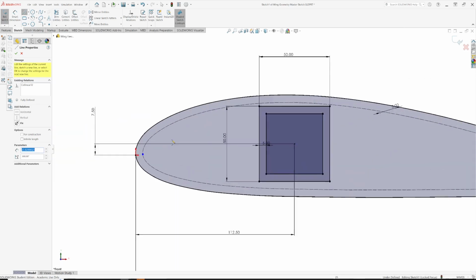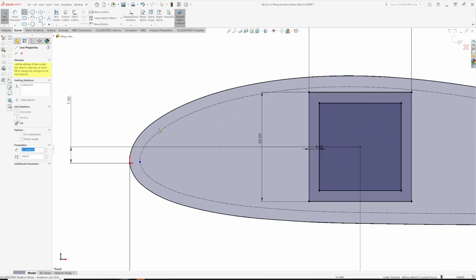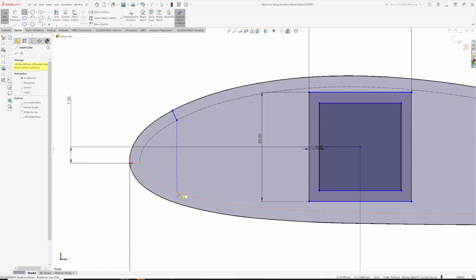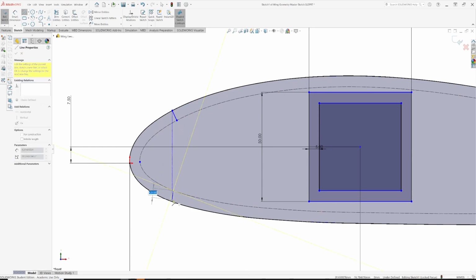The other thing we need to do is a leading edge part, because if you're covering this, you can't just have film coming around a curved edge like that. It'll collapse in the middle. So let's do the same here. It's not particularly critical where you put these, it's up to you. Let's do two of these on either side.